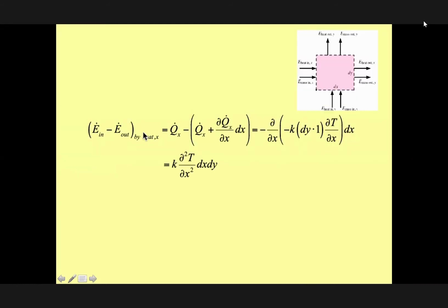Let's look at by heat. By heat, it could be conduction, okay? Therefore, energy comes in by conduction to this fluid, and energy leaves by conduction. As we did for the solid, we mentioned Qx represents conduction coming in, and here conduction leaves, okay? And that's the term, the difference between this term and this term, this cancels out, and this becomes the result of this one. This d over dx of Qx means the Fourier equation. Therefore, this represents energy conduction in the direction of x, okay?